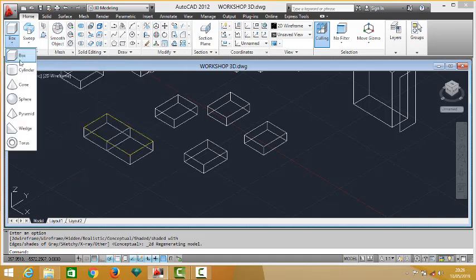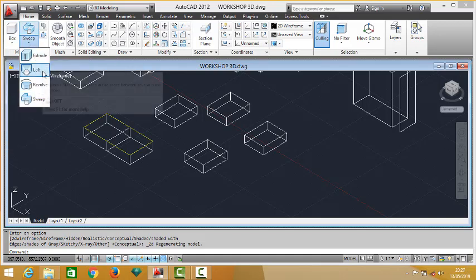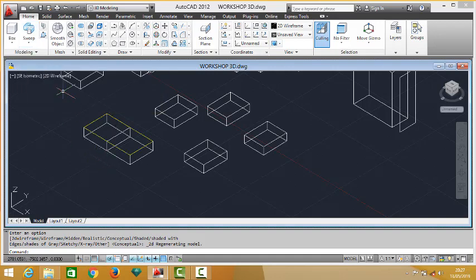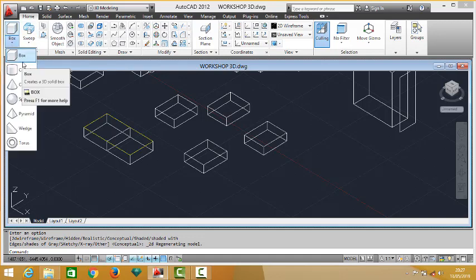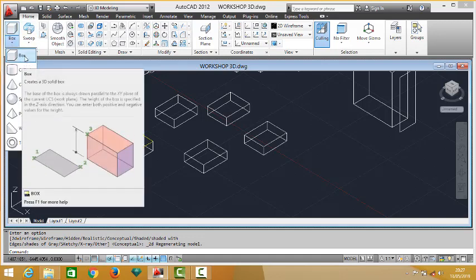That is, you are to use any of these primitive shapes to draw the object. You cannot draw a 2D profile and use a 3D command such as extrude or sweep to act on it, and then smooth it up. No, it will not work. You need to draw with a 3D primitive shape.